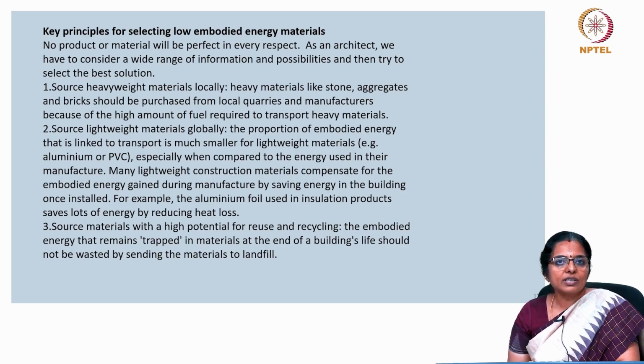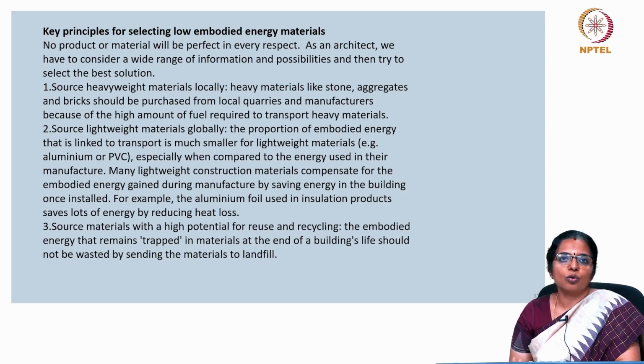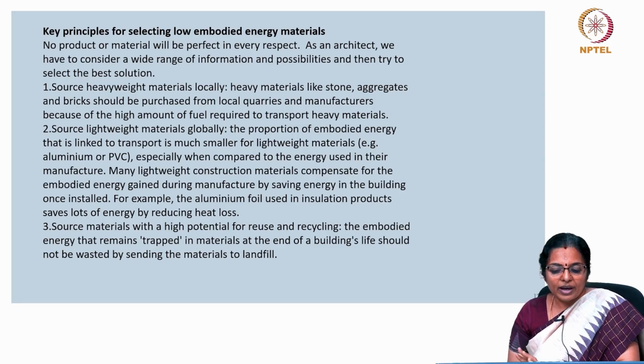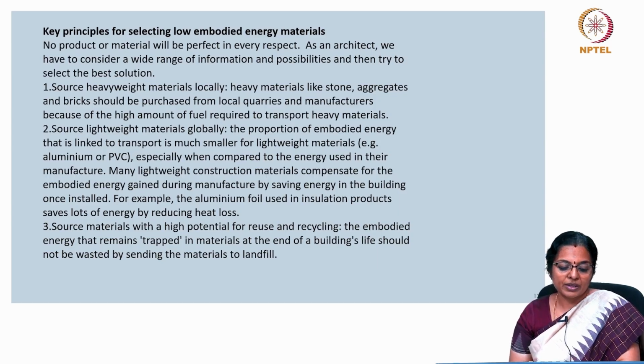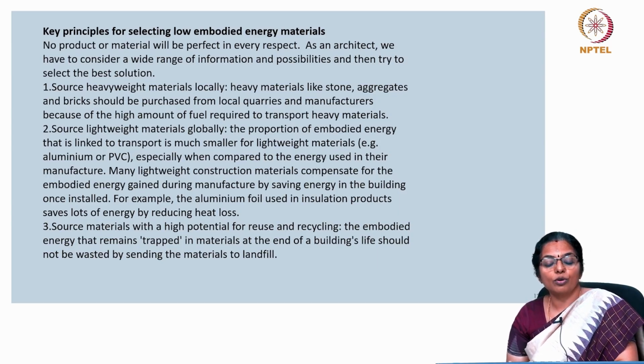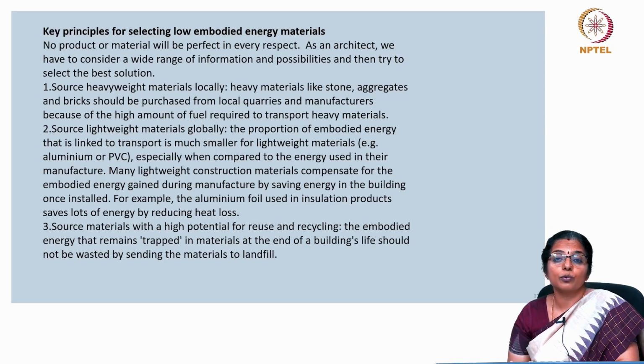Source heavyweight materials locally. So, heavy materials like stone or aggregates and bricks should be purchased from local quarries and manufacturers because of the high amount of fuel required to transport heavy materials. Source lightweight materials globally. The proportion of embodied energy that is linked to transport is much smaller for lightweight materials.